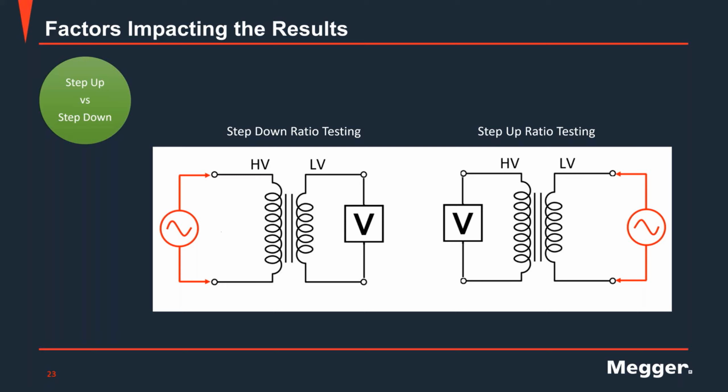So you don't know if a user will be testing transformers with ratios of, let's say, 0.5 or with ratios in a few dozen or hundreds, right? So it's easy to say, well, if I spec my instrument to have this much voltage for the output and we do step down, you know by default that you will always be measuring a lower voltage than your output, right? You're always stepping down the voltage. So that again will allow you to spec the unit to determine its insulation levels. And again, it will make the instrument safe to use in the field, right?